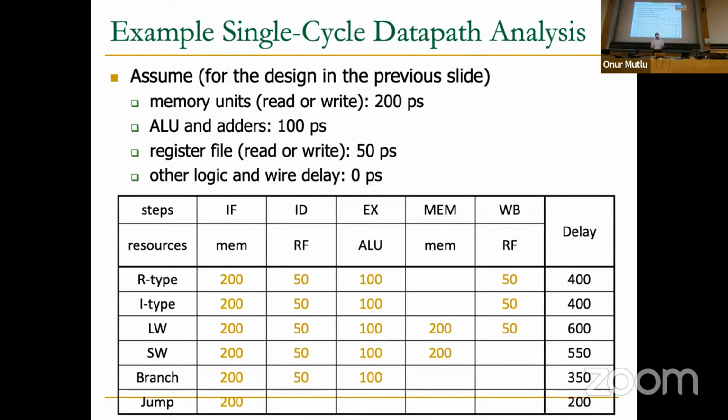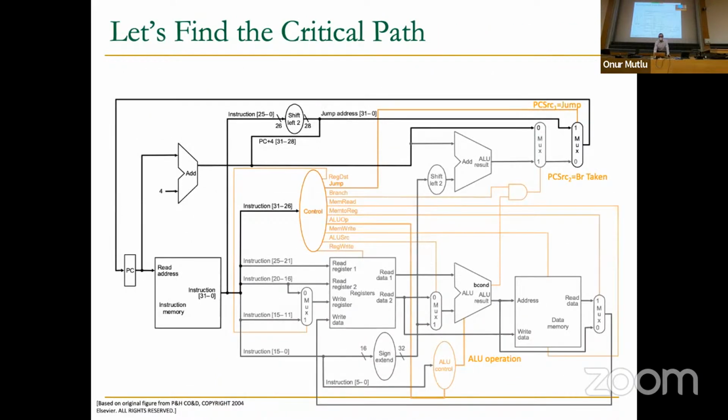But now single cycle microarchitecture forces us to determine the clock cycle time based on the worst case, meaning the longest instruction to process, in this case, load word. If you had a much more complicated instruction, it would be that one. It could take 10 milliseconds. That's why this microarchitecture design is not very good, and we're going to talk about that now.